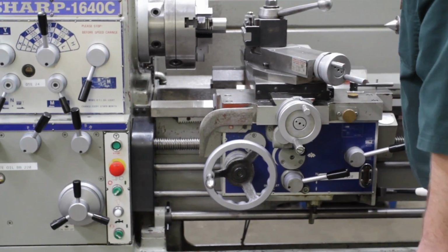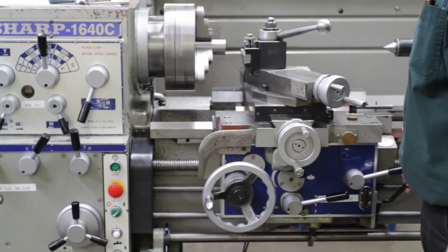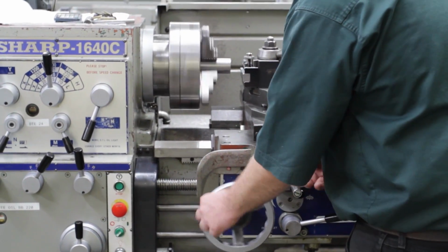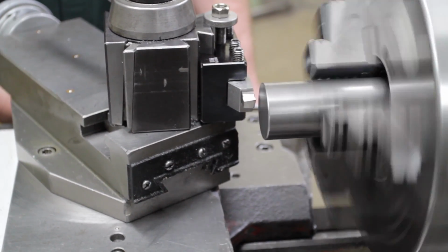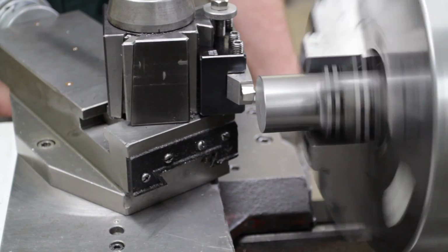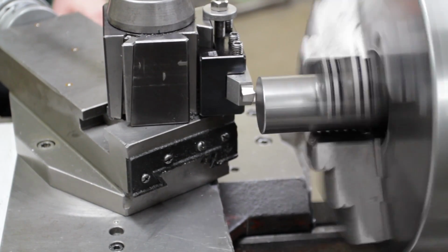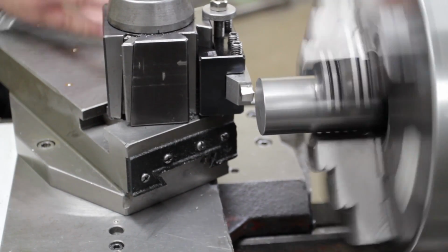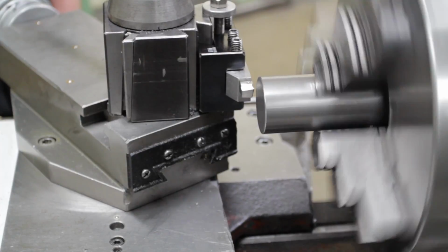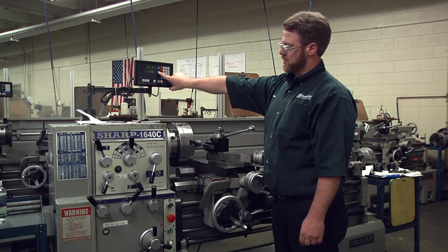So the next step is starting up the machine at the proper RPM that we already have set. And then you want to bring your tool bit close to the material. All right, so let's bring it up just until it touches the end of the material, and you'll see it scrape the end. And then you will take the X hand wheel and bring it counterclockwise. That brings the carriage back away, towards you, away from the material. And now at this point where it's touching, I'm just going to zero the Z-axis.